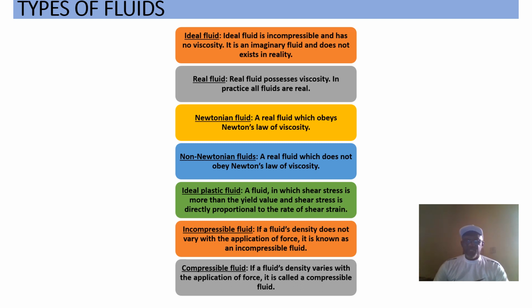Newtonian fluids, we've said that, obey Newton's law. Non-Newtonian fluids do not obey Newton's law. Ideal plastic fluids, in which shear stress is more than the yield value, and shear stress is directly proportional to the rate of shear strain. Incompressible fluids and also compressible fluids.